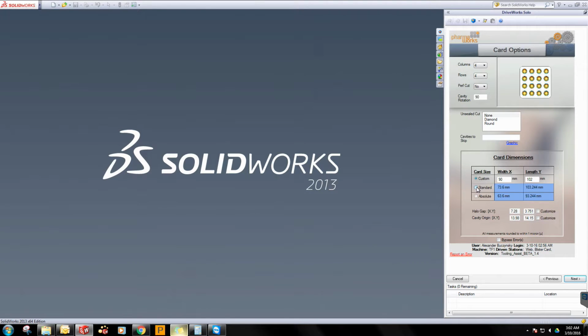Now a nice thing is if we go ahead and select the standard button, these values will automatically just be rounded up, so you have nice values here. Also, like I've said before with the hovering, if you hover over those values, it also tells you, because this is a TF1 machine, that's going to be our max values in the X and Y dimensions for our card. So I'm going to go ahead and select custom because we never would want an actual standard displacement, like a card length that's 73.6, because we'd rather have something that's rounded up. Less significant digits are better.